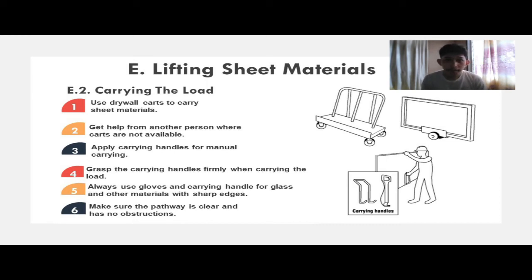So the best thing to do is to use drywall carts to carry sheet materials. You can also get help from another person when carts are not available. You can also apply carrying handles for manual carrying. You should also grasp the carrying handles firmly when carrying the load.